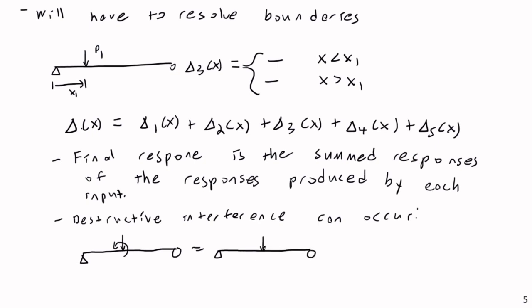The point load deflection is just going to be a nice, friendly, simple thing like this, deflection downward. And the couple is going to be a deflection something like this. We're going to end up with an inflection point in the middle. So something more like, kind of like this, in a way. This is going to want to cause things to twist to the left here.